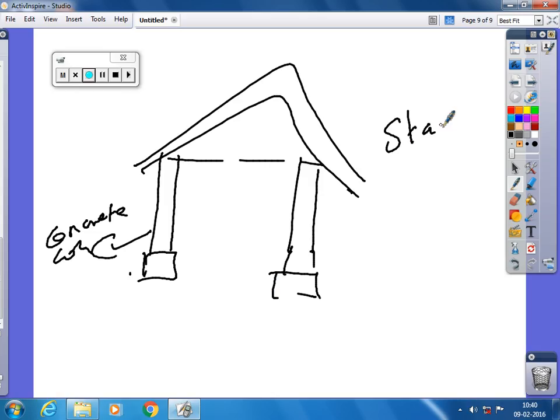Have you heard about stacks or stick piles? A lot of sticks are kept in between to keep a distance between the timbers, to give a good space. When you give a good space and don't attach each wood together, air circulation will be fine. When the timbers are very close to each other with no space, the air cannot move inside, and you cannot remove moisture from all the sides of the wood. Clear?